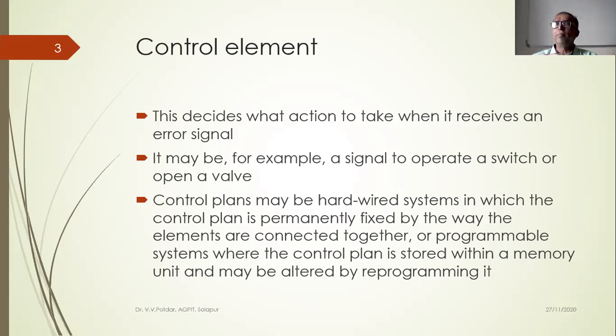Or if my operation is maybe a repetitive sequential operation, in that case, whatever will be the changes in the system parameters, those I study beforehand, and then I prepare a program. So my programmable logic controller, or maybe my microcontroller, or maybe my microprocessor, would work in a pre-programmed manner. If the error is so and so, take this control action. If the error is so and so, take this control action. If the error is, say, C, take this control action. I decide the control logic, and accordingly I program the controller. It will be in auto execution mode.